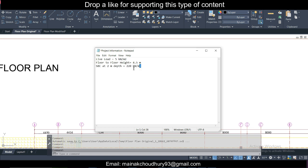So this is the SBC which has been taken, and the foundation depth will be given as 2 meters. Plinth height is also required, so we'll take it as, let's say, 0.4 meter, and take this into consideration. So the total foundation depth will be 2.4 meters. So these things will be done.